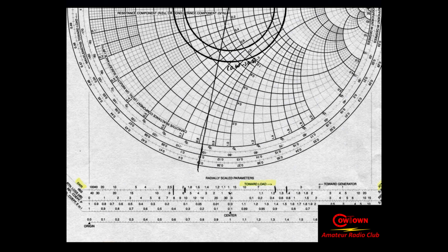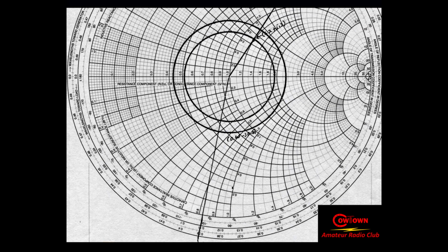So my hand is pointing at prime center over here to the number 4. That's my 1 dB. So now I'm going to take that 1 dB, that new radius, and I'm going to take my compass and draw this second outlying circle out here. Where this line crosses that circle, that's going to be the normalized, corrected impedance at my antenna feed point.